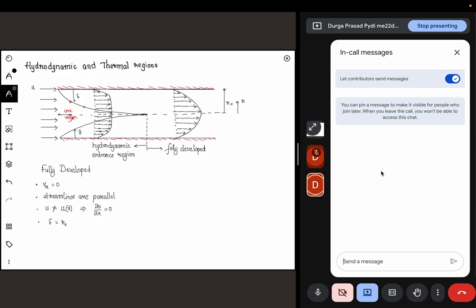So if you are far into the domain, where your L is very high compared to the separation of the plates, then you will be in an internal flow like this and this. But if L is very small, then you can consider these two plates as non-interacting, or basically you can consider the flow to be external and use the boundary layer equations that we derived in the last two lectures. Now here we have two different regions. Let's say we are dealing with internal flow, so the length is very large.